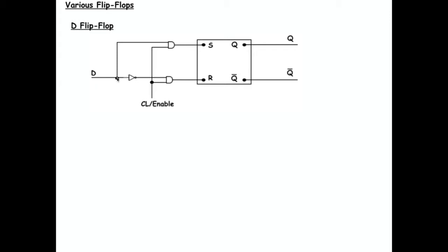So we have a bit of wiring before that D goes into our flip-flop gate. We're going to put a splitter, and we're going to direct the true value of D into set and the complement value of D into reset. That's what we're doing. Now, forget about the clock, forget about the controller for a minute.